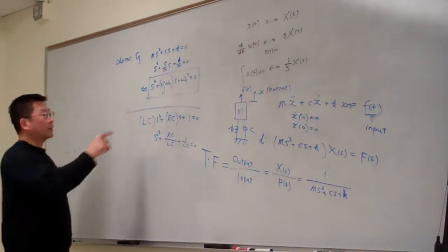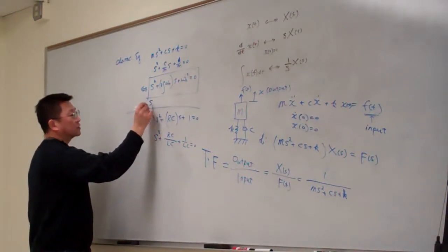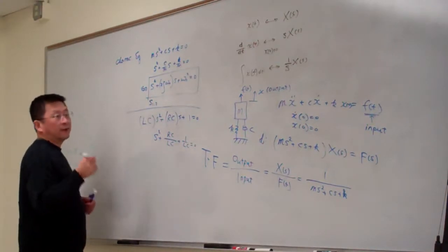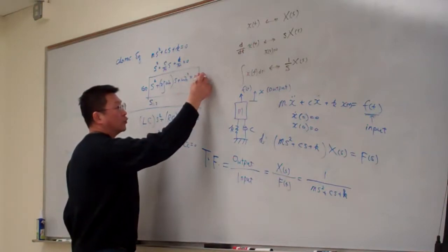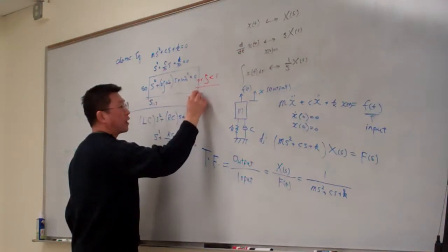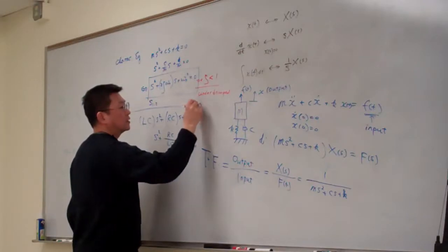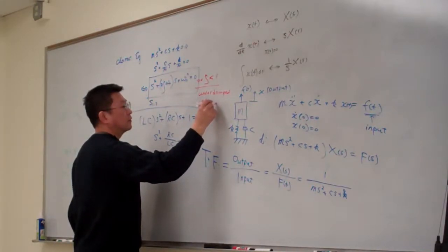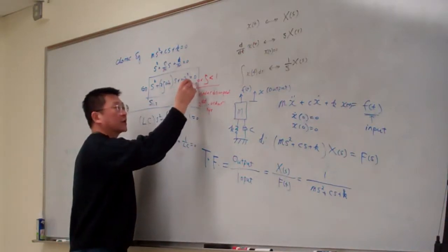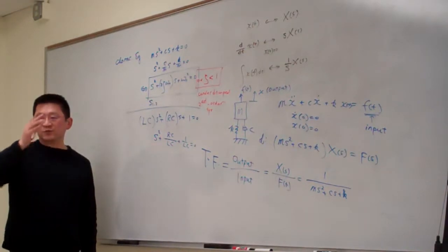Okay. So from here, last time we did this is the pole. And so that means here we can solve for S1 and S2. And in particular, for our controls, we are more interested in this case. We call it underdamped second order system. This is the particular case we are very interested in because this case can produce the oscillation response.